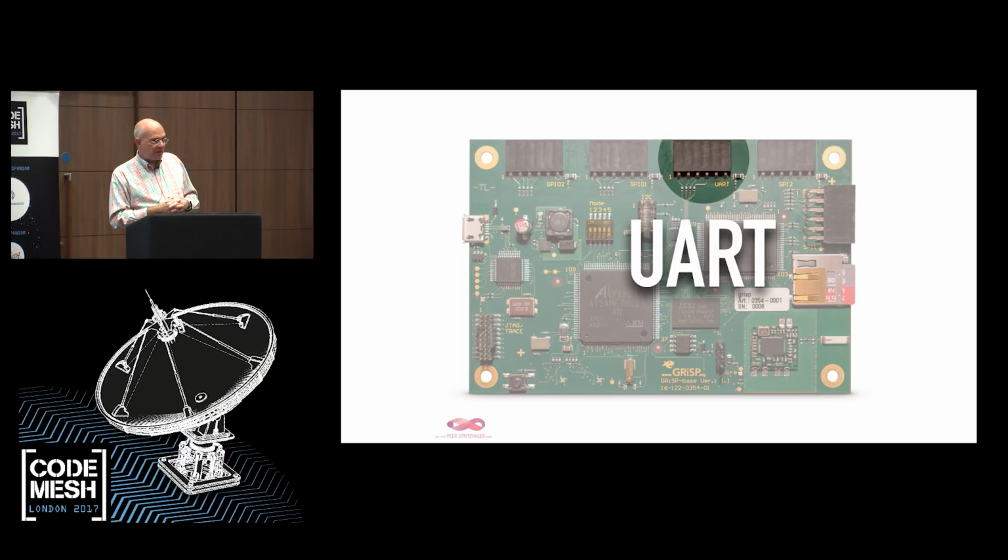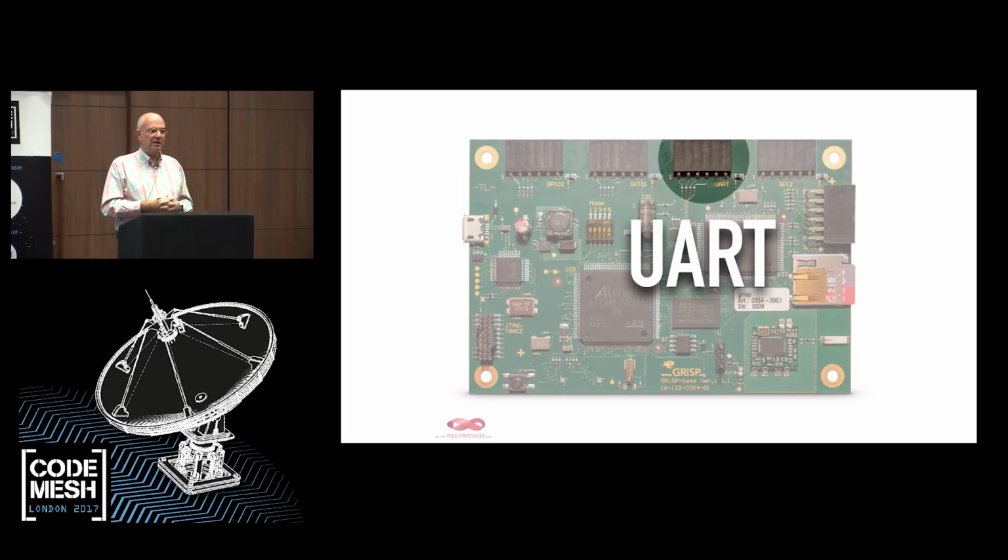There's one plug which is called UART, which is a 3.3 volt UART, so it's not like the normal serial connector we had on the PC like ages ago, or you can still have as a USB serial, but you can plug in a converter that makes it to have the normal, because the normal thing is plus minus 12 volts signal strength, and there's also standards for industrial things, so you can get all kinds of converters here.